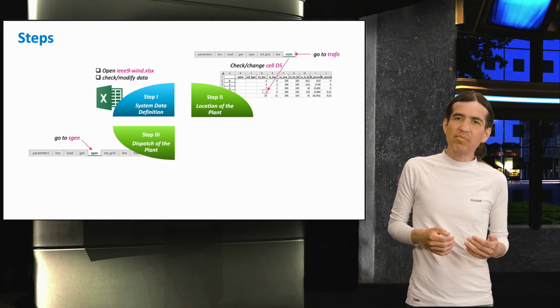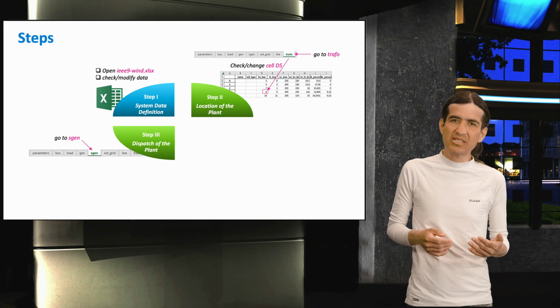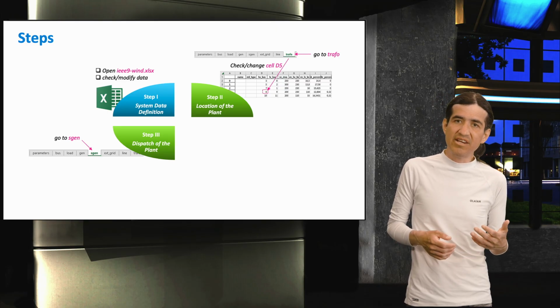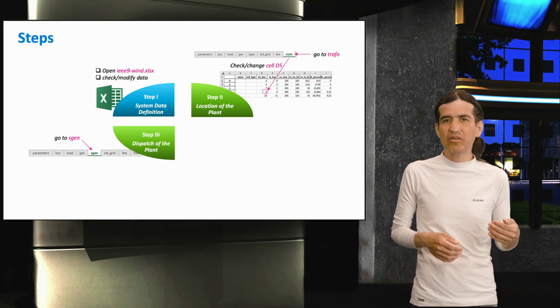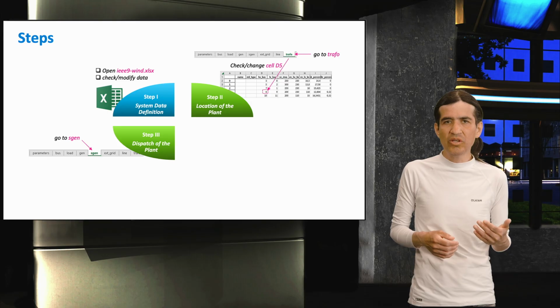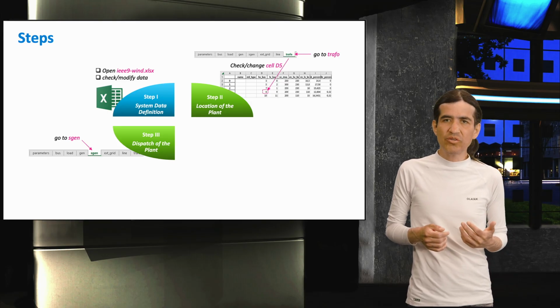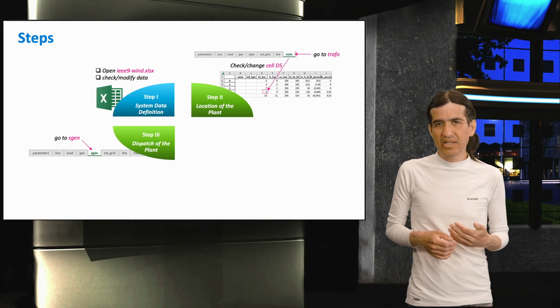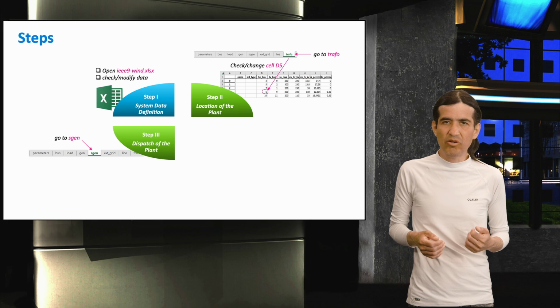A desired active power dispatch can be enforced by defining equal values of minimum and maximum active power outputs in cells M and N. A desired reactive power dispatch can be enforced by defining equal values of minimum and maximum reactive power output in cells G and H. So, in the example shown here, the wind power plant has an active power output of 180 megawatt and a reactive power output of 0.